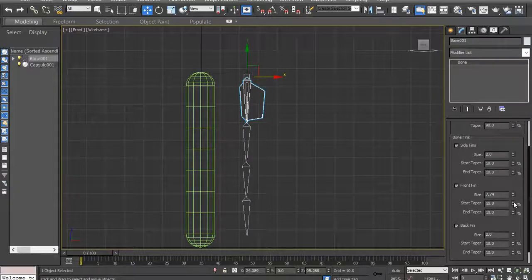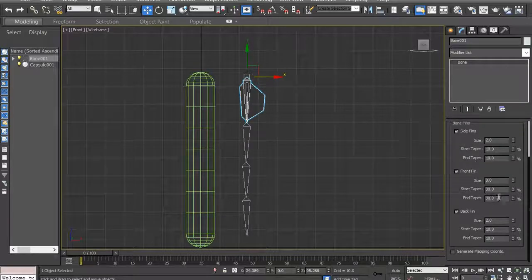It's kind of tricky to even see what's going on there, but you can see it's sticking out at a larger angle. Let's just type in 30 there, and then we'll type in 30 down here, and that's about 8. Let's make that 8. You can see that's the shape of our fin, and now we've got a numeric model for the size of the fins that we would like to use here.